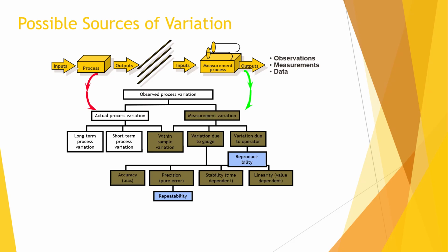Your measurements are only as good as the appraisers, only as good as the instruments used, and those instruments are only as good as if they're calibrated, right? There's a multitude of things involved, and the whole point here is making sure whatever measurement tool you use, especially if it involves human appraisers, that they are trained.